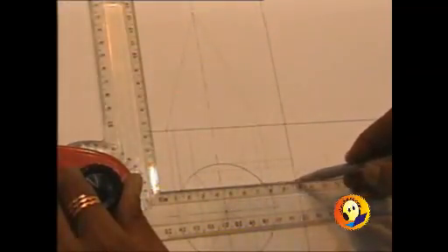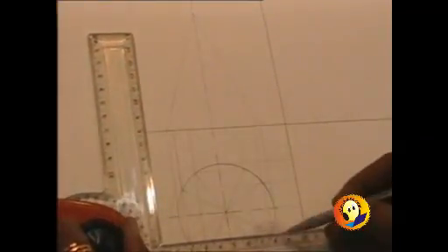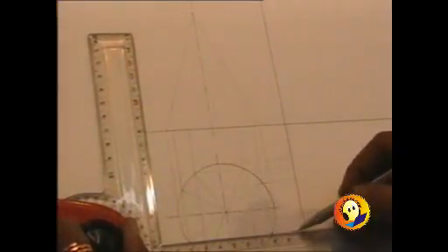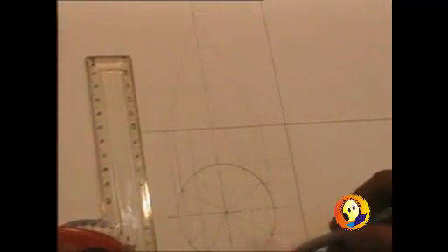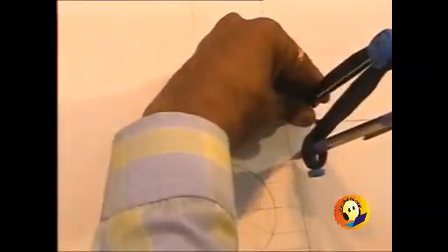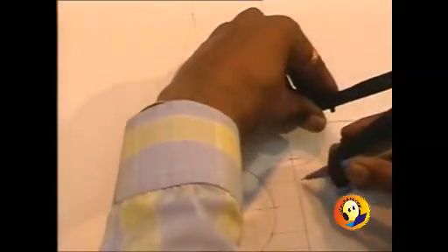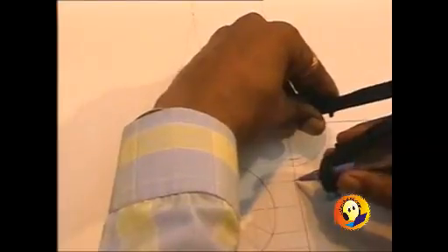So we are required to take these 12 points to the side view. And then to complete the side view, we are required to rotate them with the point of intersection of the vertical line with XY. So the same considerations again and again. To obtain the side view, there is no different procedure as such.